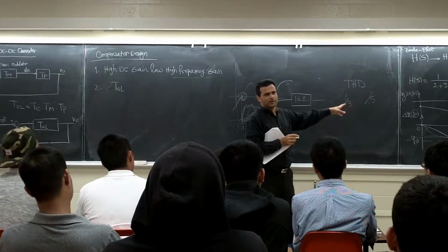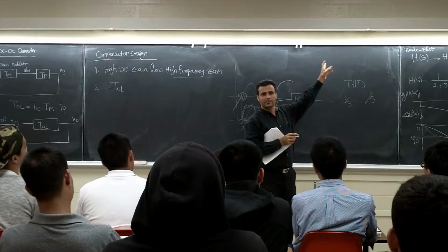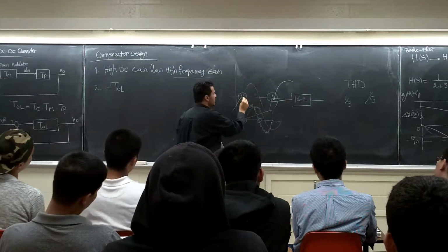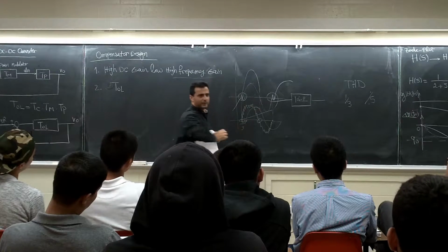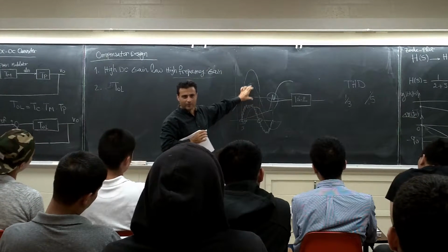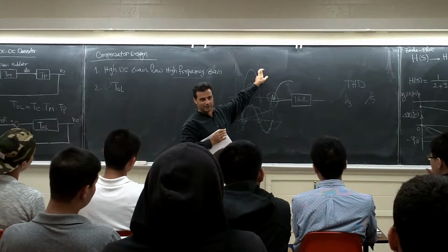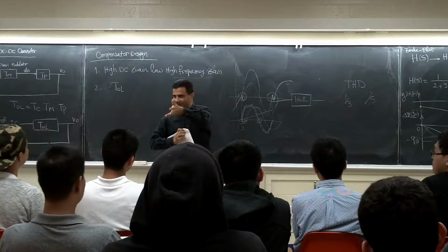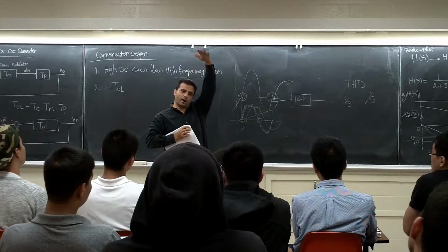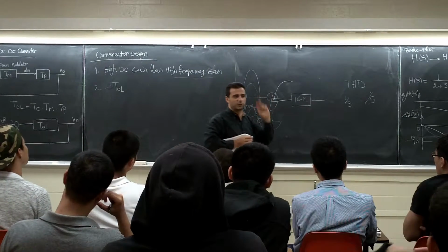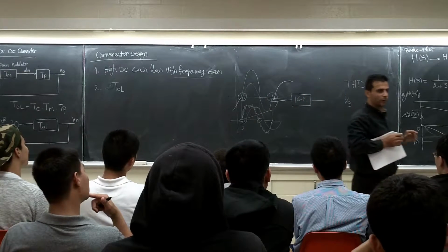What I'm saying is, when the power goes up, this is going to get better and better. Look at here, you see the same thing, but the bigger current is here. Yes, you have this effect. Overall, the fundamental is much bigger, right? It's going to help you with the THD, as in the few examples we solved. When the power goes up, it helps with THD. When you have this one, the THD will be like 3%, 3.2%, right?